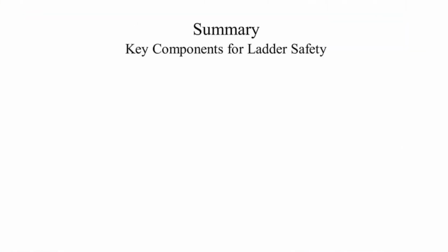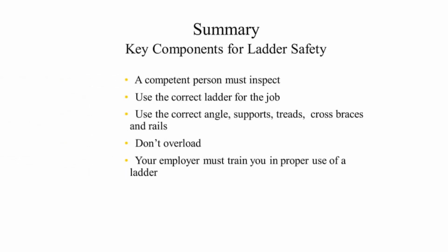The summary of key components for ladder safety is: a competent person must inspect the ladder before use, use the correct ladder for the job, use the correct angle, support, treads, cross braces and rails. Don't overload the ladder. Your employer must train you in the proper use of a ladder.